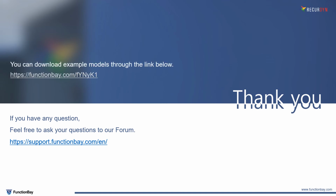This is the end of this seminar. The more proficiently you can use PV and PP, the more efficient RecurDyn modeling becomes. In fact, RecurDyn expert users are working with dozens or hundreds of PVs and PPs in their model. I think it would be great if you make it a routine to define values or points as PV and PP. I recommend to try to create your own PVs, PPs, PVC and PPC as I introduced in this seminar.